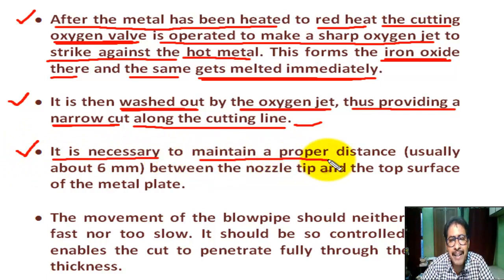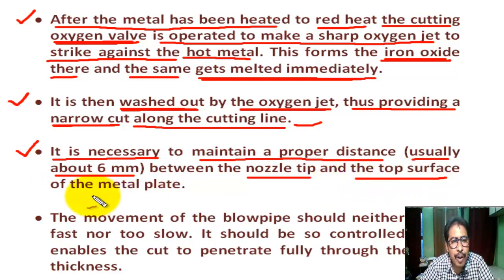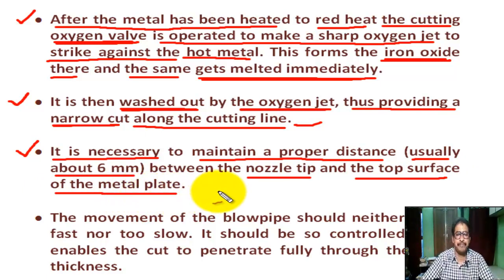It is necessary to maintain a proper distance, usually about 6 mm, between the nozzle tips and the top surface of the metal plate.